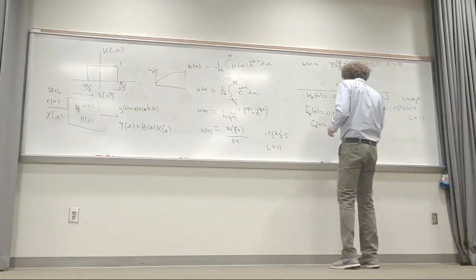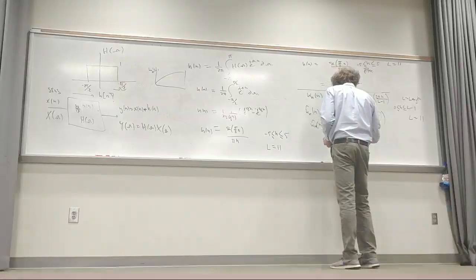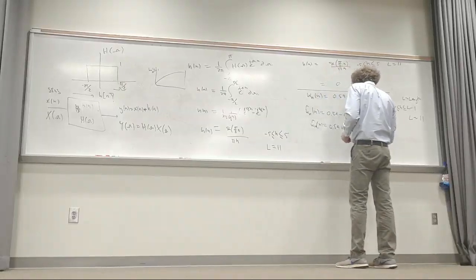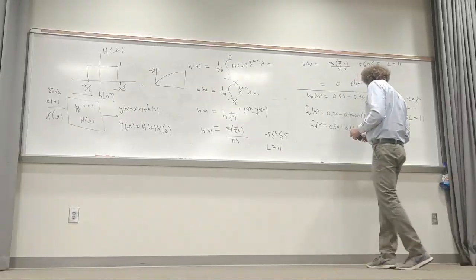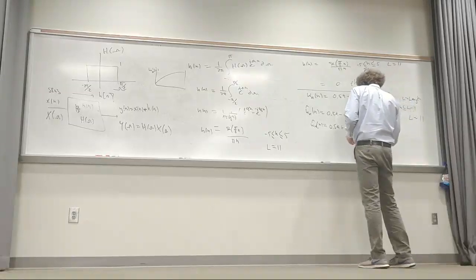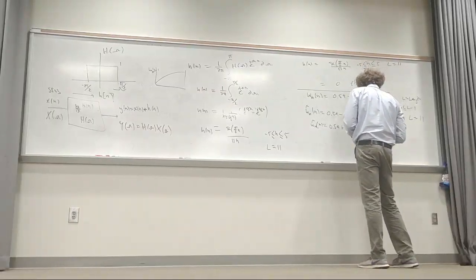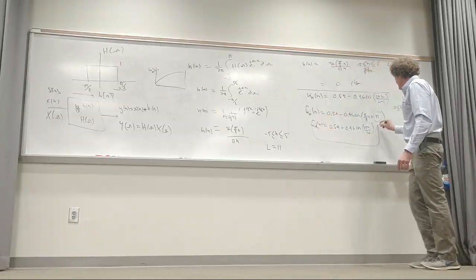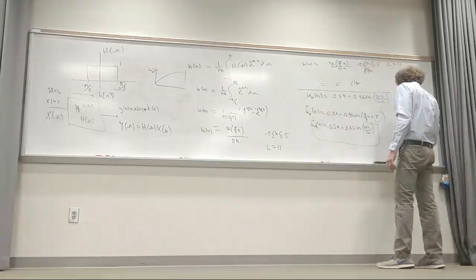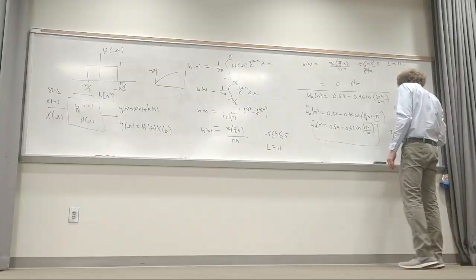So this is going to be now 0.54 plus 0.46 times cosine of simply 2 pi n over 5, you can put 2 pi in if you want. I think he does leave that there. You don't have to. 2 pi n over 10, pardon, over 10. Now, this is the window that now is adjusted, and it's good for n greater than or equal to minus 5, less than or equal to 5.